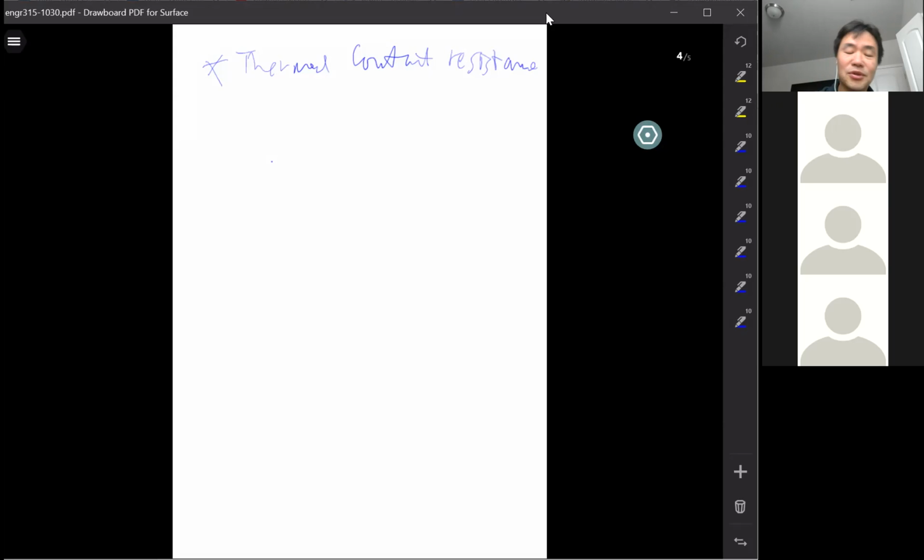Okay, that's very important. So for this system, since you know T1 and T3, you have three pieces in that system, right? A and B and the contact region. So you can easily use the beginning and the end to find out the heat transfer rate, right? That heat transfer rate will be exactly the same heat transfer rate going through that contact region only. Okay, does that make sense?